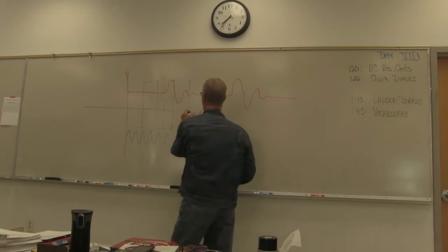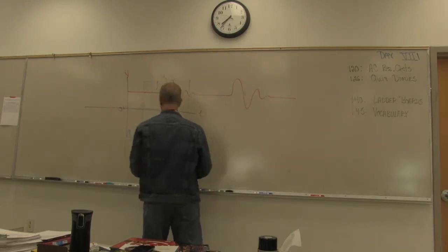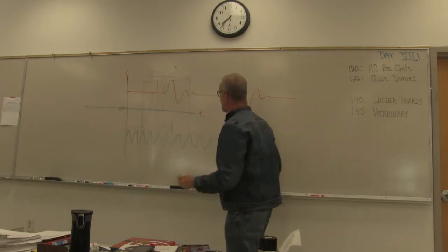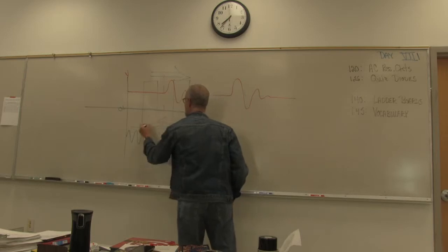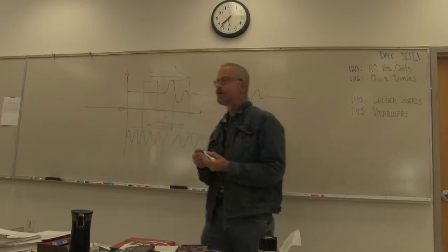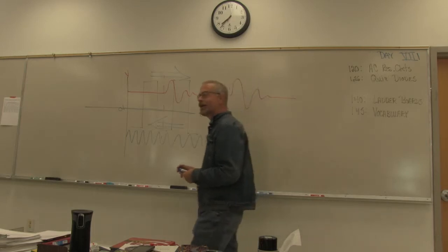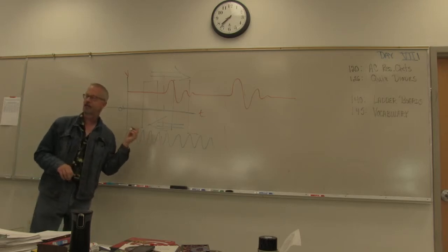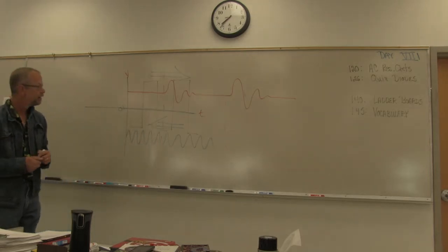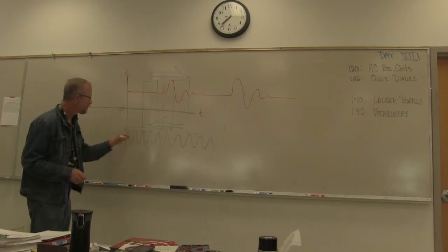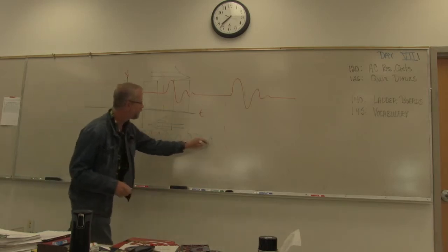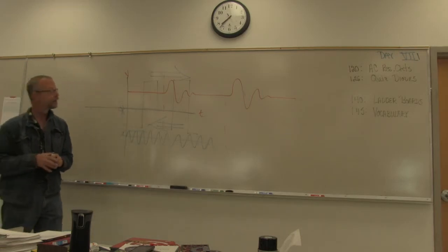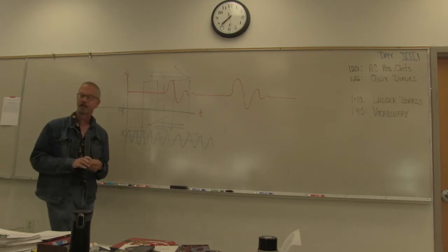Okay. Above the 0 volt line, everything goes in this direction. Below the 0 volt line in terms of current, everything goes in that direction. So in order to really be considered alternating current, it must cross the 0 volt line. So this is not really AC, it's an AC waveform, but what it is, in this case, is a certain value of AC with a negative DC value added to it. Okay, so you're getting DC plus AC in this circuit.